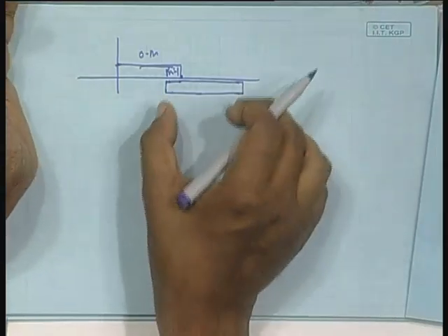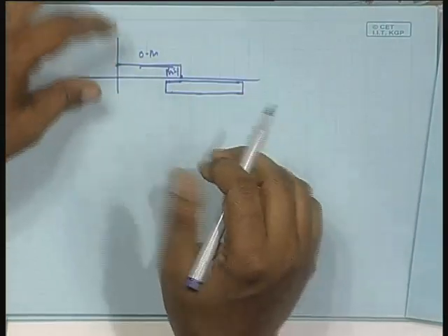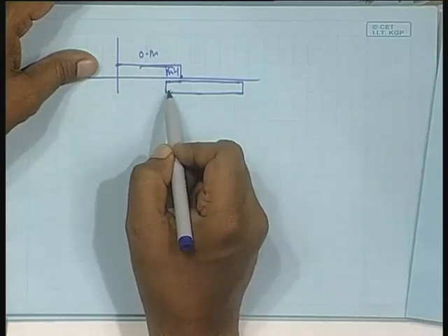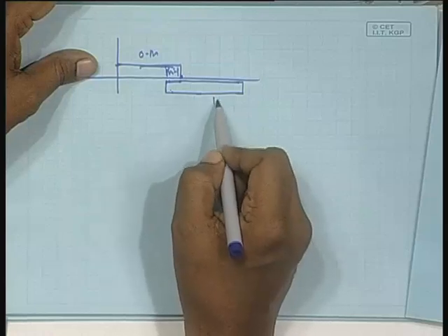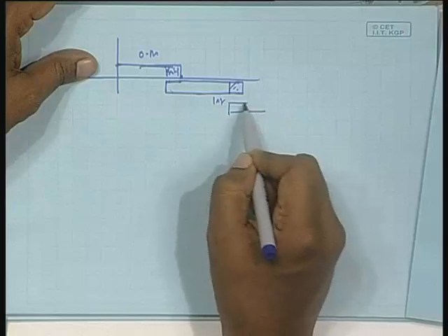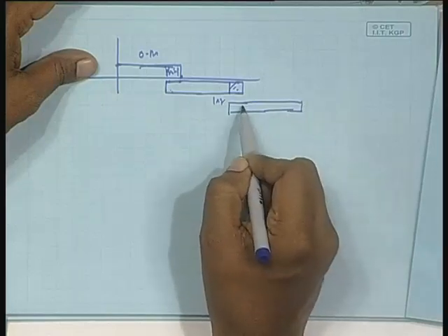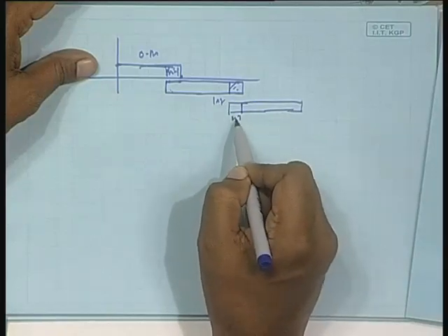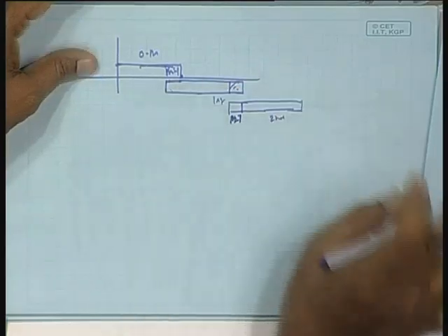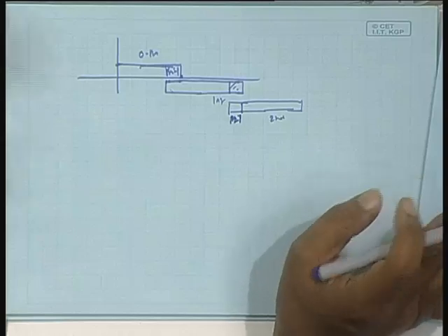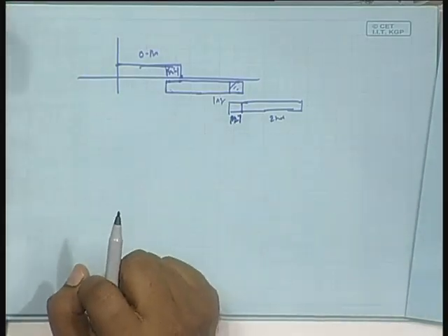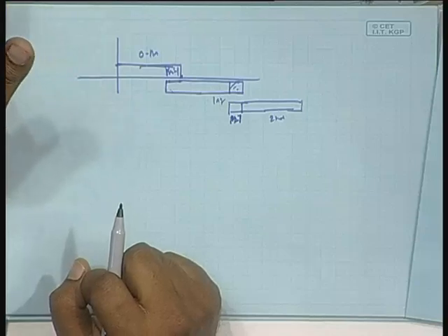Data is same, I am just showing as a two kind of strips. This is one strip of data, and the last m minus 1 components again repeated in the front of this next block. There is block number 1, again this guy is repeated, m minus 1 length, second block and so on. Now, if I do that, and now suppose I am convolving with a small filter h n whose length is capital M.